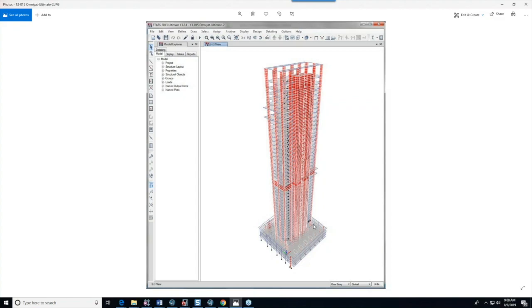But you have to be very careful to make sure that even if the walls were continuous down through to the bottom of the basement, you may have some additional walls that are going to start to pick up the load. And if you were to assign a rigid body diaphragm at one of these heavy transfer slabs, then you're not going to be able to see what kinds of diaphragm shear you have in those slabs. And it would probably behoove you to model these as semi-rigid, and that way you could track how much shear you have in these diaphragms.